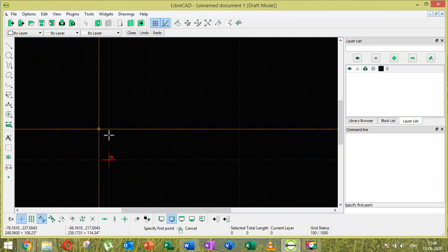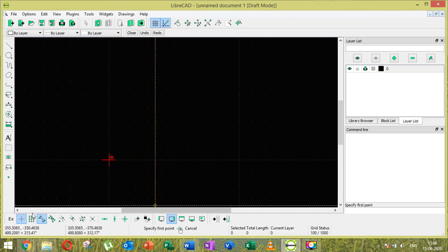And one important factor you want to consider here is that at the bottom you can see this cross line, the snap on grid, the free snap, snap on endpoints. I will tell you what this actually is, because this is important when you draw complex drawings and you want your drawing lines to stick to, sometimes the center of the line, or the ends of the line.